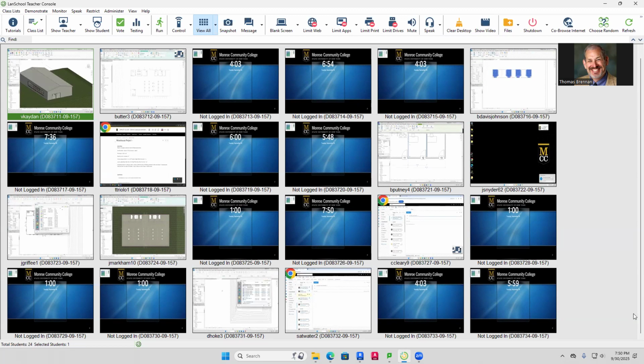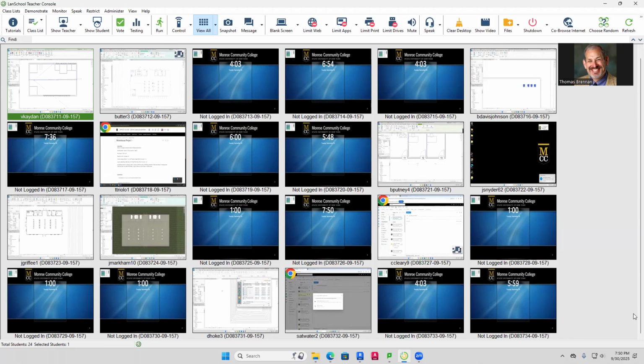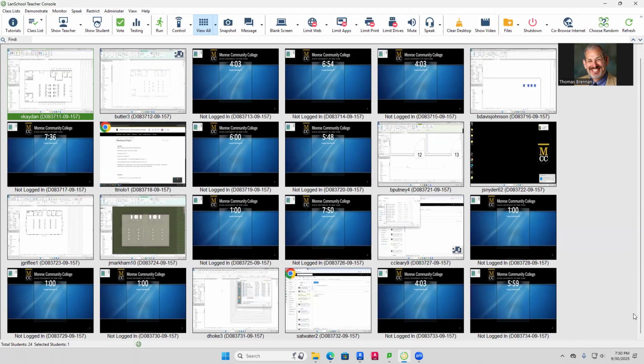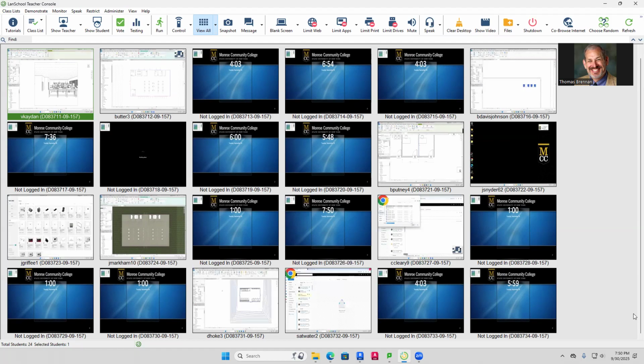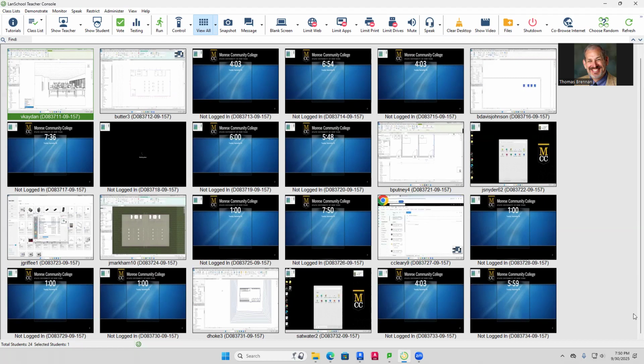Okay, you got that saved? Yep. Go and close out there. File and go to close. Okay, and then go to new. Click on new. And then go over to browse. Browse to your desktop. So click on the same desktop over to the left. There it is. And then you want to click on the data model.